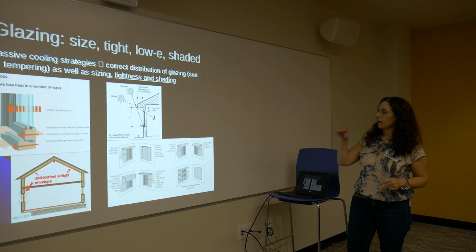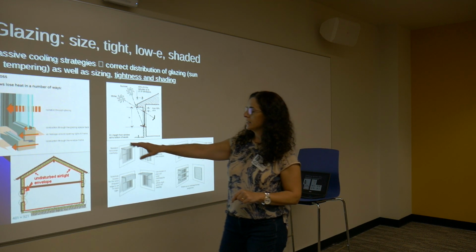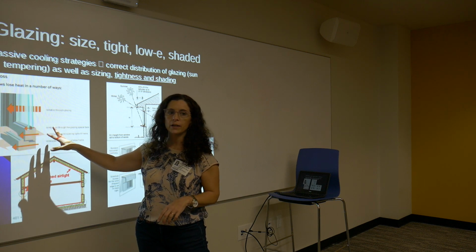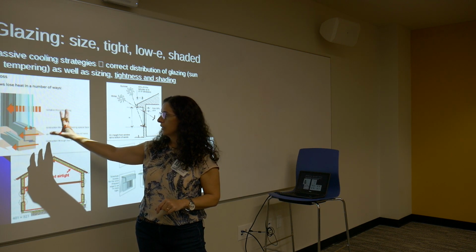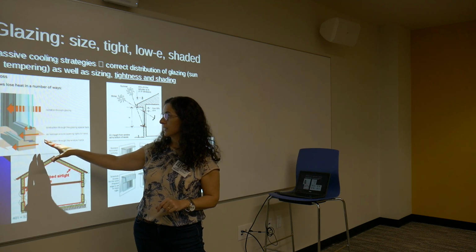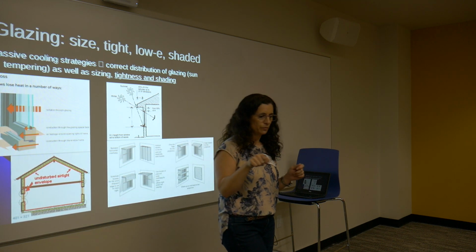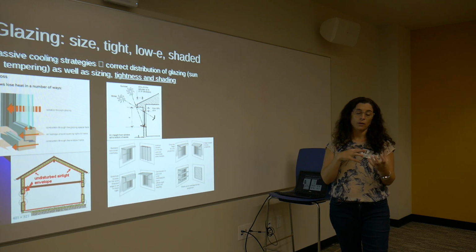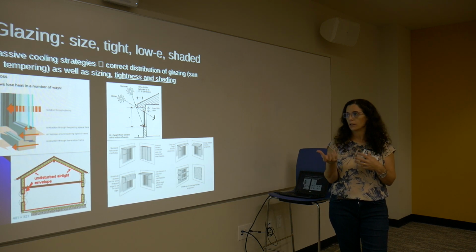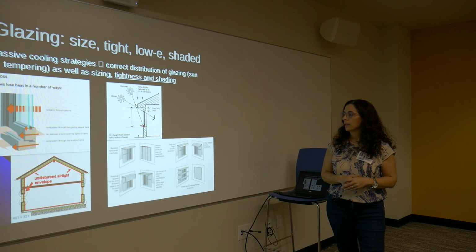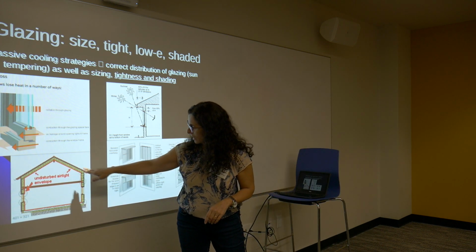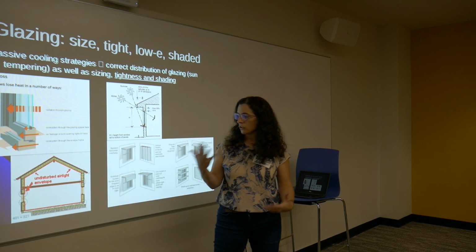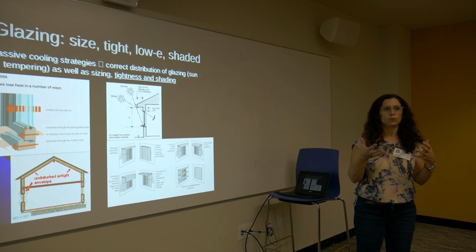Okay. So again, I was telling you about how tight. This is very important because of all the infiltration we can have, cold air in winter. To have a very good window is important, and also the whole house needs to be tight, so we can keep the heat if we need, or the cool if we need in the summertime. Again, all that is showing that there is insulation all around the house. It's either insulation or high mass, so concrete or stone.